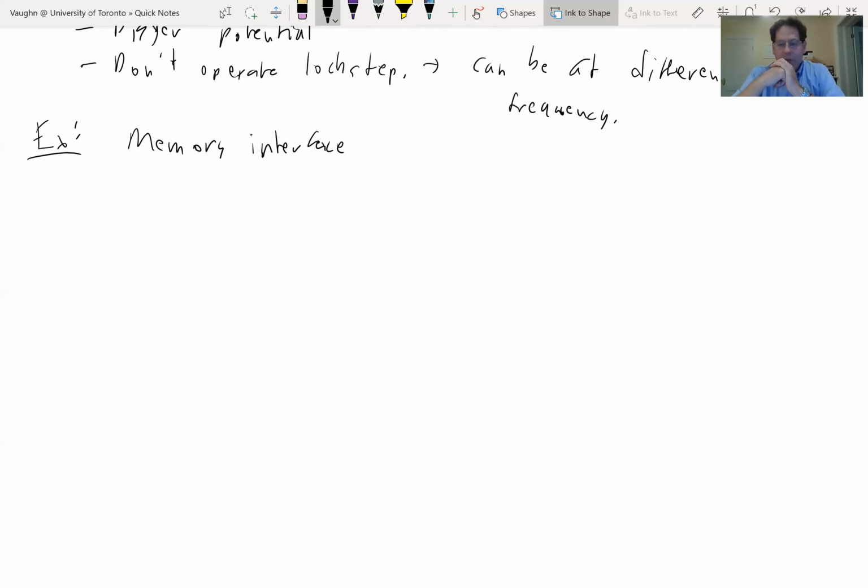And memory interfaces are one of the most important I/O protocols. You want to get high bandwidth, you want to get low latency, and an FPGA has an additional bunch of constraints. They're programmable, so we want to be able to connect to all sorts of different kinds of memory. FPGAs don't typically build an interface just to one kind of memory, like DDR3 or DDR4.